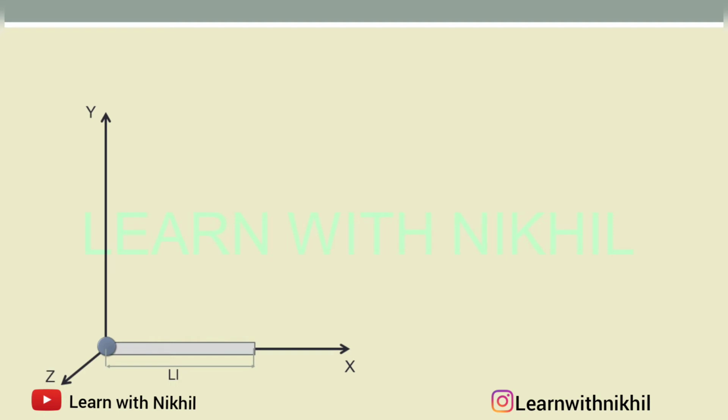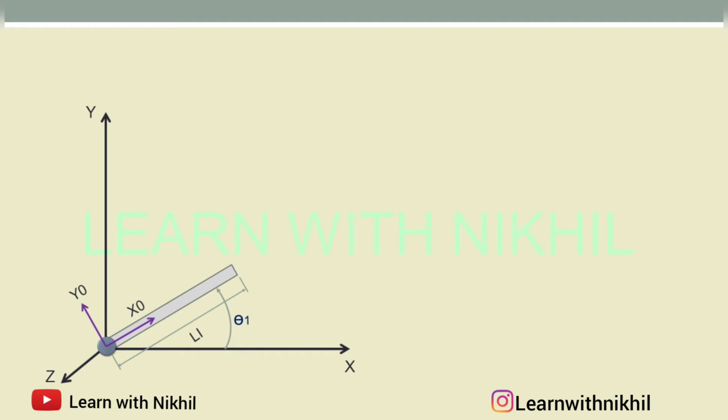Now as you can see here, this link is moving in the XY plane and the Z axis is coming outward. So if I have to change the coordinates in the XY plane, we have to rotate it along the z axis. So you have to rotate this link along this z axis. This is the current x0, y0. Now we'll rotate this about the z axis. This will be the new x0, y0, with a rotation by an angle of theta 1. So we have rotated this link by an angle of theta 1 along the z axis.